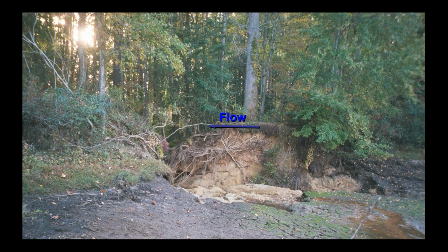There was a tree right where this void is, and you can tell, obviously not a very well maintained dam, but that tree got blown over. It took the root system with it, and you can see the root system of the next tree that's built on the dam, and you can see how invasive that was in the embankment.